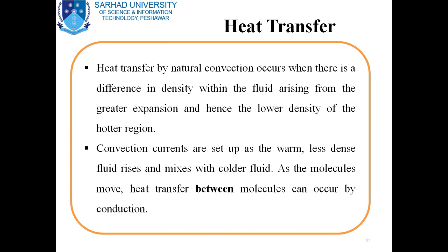That's why after some time the cold water will be at the bottom, and the water that warms up, as in the example of the electric rod in the container, expands. After the expansion the density becomes low and the molecules travel toward the surface because of the low density of the hotter region. Convection currents are set up as the warm, less dense fluid rises and mixes with colder fluid. As the molecules move, heat transfer between molecules can occur by the process of conduction.